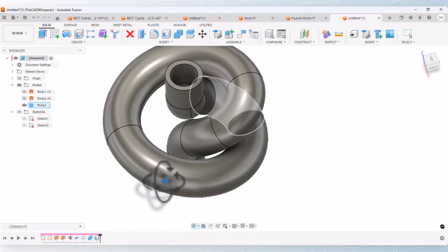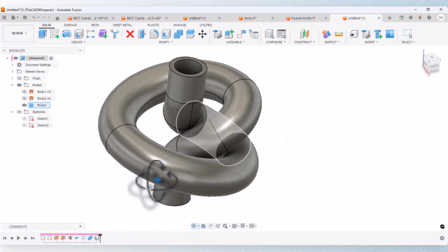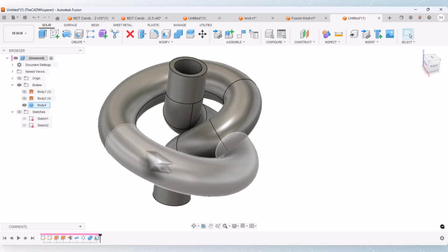And so that's it: if you can determine in two views, a top and front or a top and right side, what the path would look like in an orthogonal projection, then you can use those orthogonal projections to create the 3D path to get the shape that you want, whatever that complex curve is.